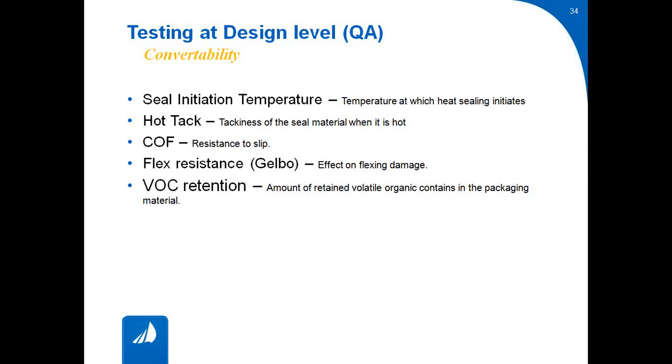Now, it may create pinholes in the pack depending on the material that we used, or the various properties that we have discussed, that OTR and MVTR, this resistance can get impaired. So we do a control flexing of the material and check it before flexing and after flexing so that my performance is assured.